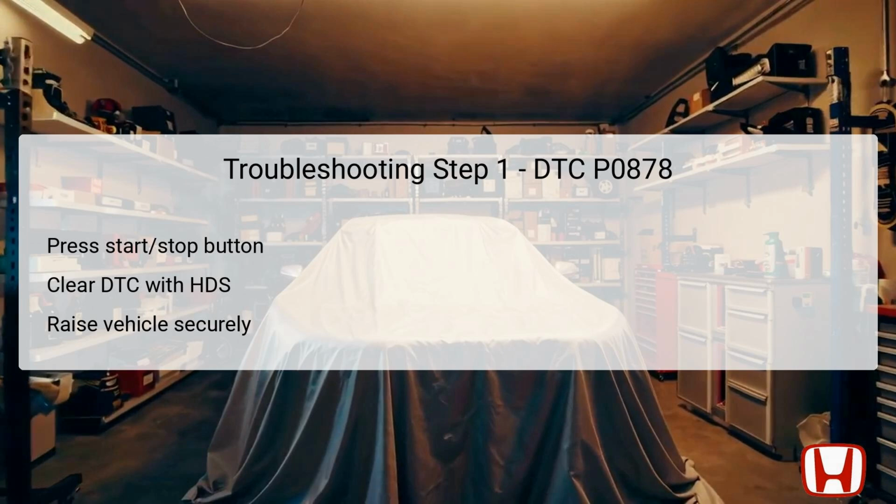After clearing the codes, safely raise the vehicle on a lift or use jack stands to ensure it is securely supported, with the front wheels able to rotate freely. This allows technicians to conduct the subsequent tests needed effectively. At this point, it is essential to proceed cautiously to ensure the vehicle's safety during the diagnostic process.